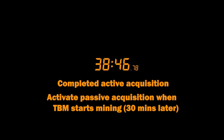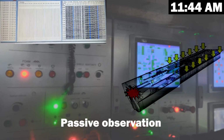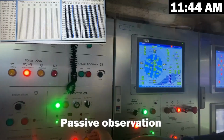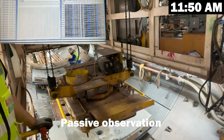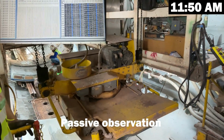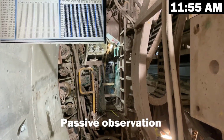We also collected the vibration signal from the working TBM, which is called passive seismic data. In the passive data observation, the working TBM works as a source rather than activating vibration manually. We can hear from this video that the TBM is very noisy when working, so the working TBM can give us stronger vibrations, getting a longer detection range.